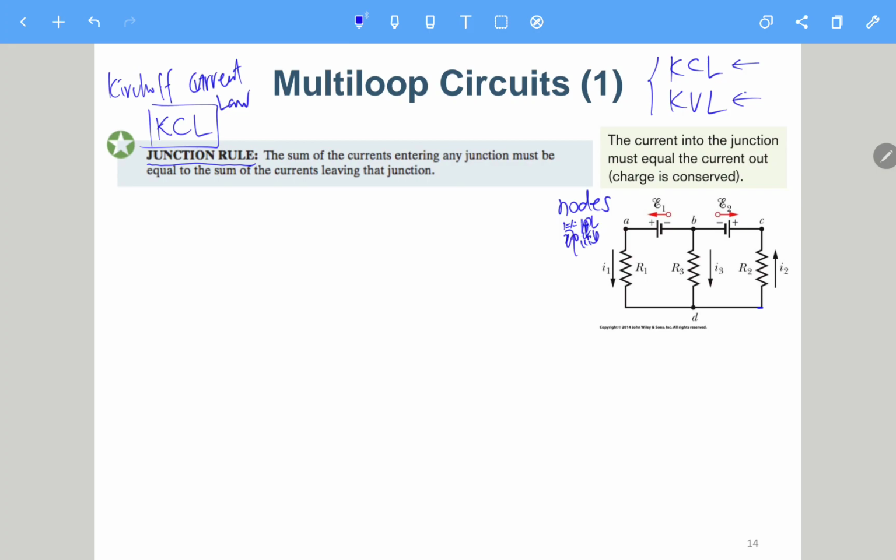Okay, so for any circuit you can define any one node to be the ground. Define only one of them to be the ground. So let's say we can just make this one the ground. This one you already know the voltage should be 0 volts, so it should not be an unknown. And then the only remaining nodes are 1, 2, 3, A, B, C.